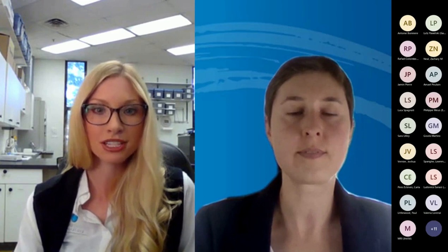For the duration of the time that these are deployed at a monitoring location, any dye that's in the water will be accumulating on them. So it's a little different from water sampling in that you have a cumulative sample versus an instantaneous moment in time. But we find that it is very useful if you are using remote sites where access might be difficult, and you might not be able to get, say, an automatic sampler down, or you don't want to camp out and just take a bunch of water samples until your dye comes through. So we use both, but primarily charcoal.